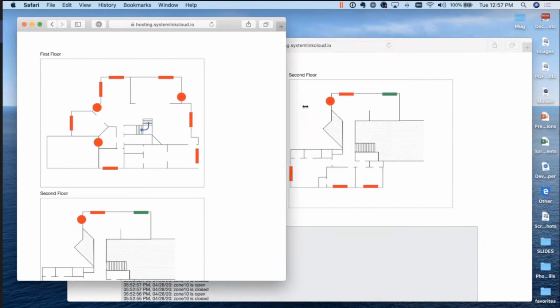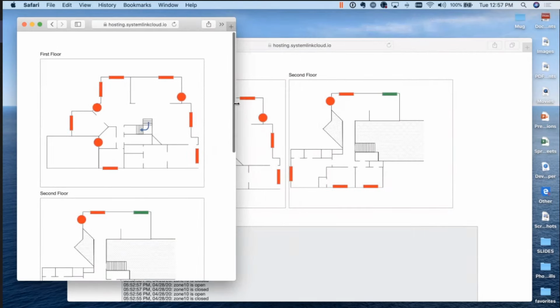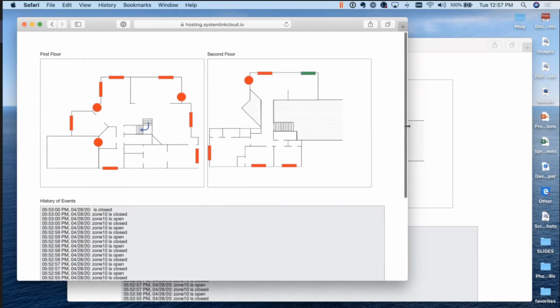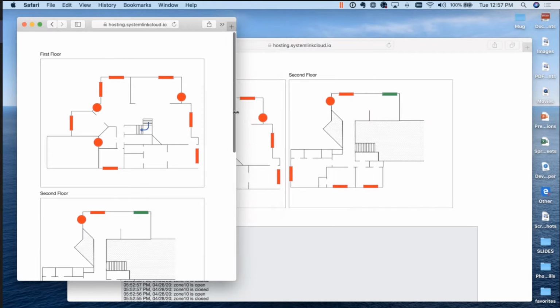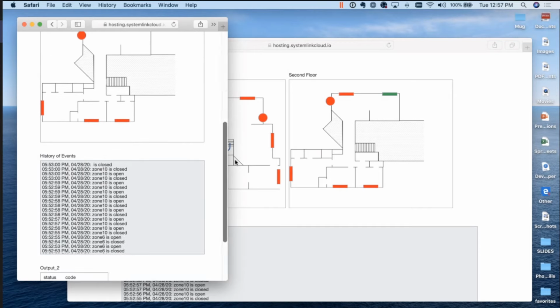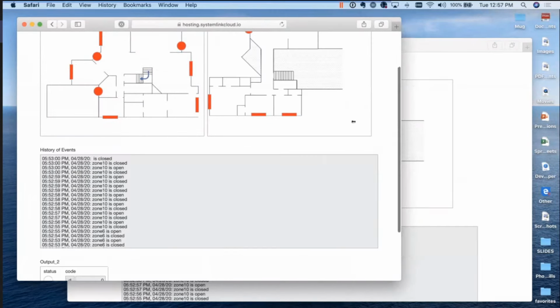And notice too, WebVIs do a lot of things that native front panels don't do. Like you can define how to resize and lay things out if you're pulling up on a phone or a tablet. Right. I haven't made this one super great for phones yet, because I just finished it a few days ago, or got it in this prototype state. But you can see, for example, the swing indicator there is resizing, while these ones up top, they're not, but they know how to wrap for a phone layout.